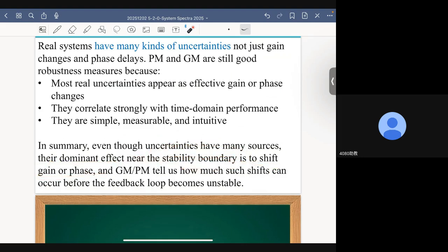All right. So if I have a lot of room, in any event, I will encounter uncertainties. So the true gain margin and true phase margin will not be the same, but if I have a sufficient amount of room to tolerate those variations, then my system has good robustness, and that makes me sleep well at night.